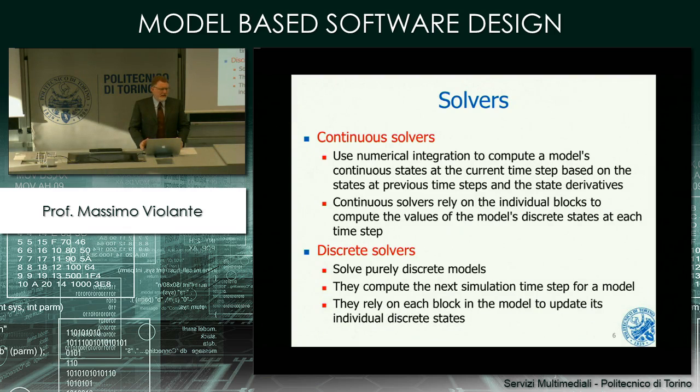This is normally the default configuration of Simulink because it is the one that provides the best approximation of your simulation. Another option is the discrete time solver. This means that the time is a discrete time. There is no infinite sequence of time instances in between two time steps. Now is time step t, then is time step t plus delta. And here you solve the model for t, and then you solve the model again for t plus delta. There is no evaluation of the status of the model in between.